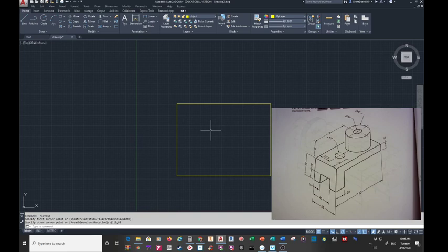And you're like, okay, why don't I just start drawing the front view? Well, there's a method to my madness. When I learned how to do this, we drew by hand. We had to figure out spacing on paper so we could keep things centered. And to me, if you figure out where your views fit inside of a box, it's going to make it a lot easier to draw the views.